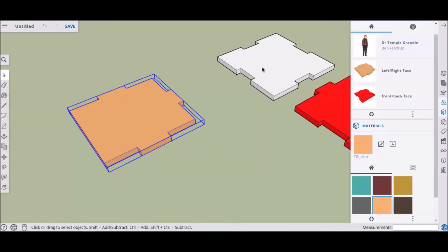Right, so I've got my 3 components now, which is what I want. Now I've got to obviously attach those to the base and rotate them round. So the trickiest part, I would say now. You've got to come over to the move section, and you want to pick on rotate, and it gives you a protractor.